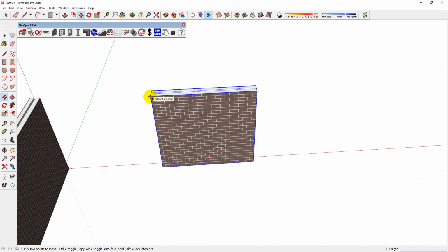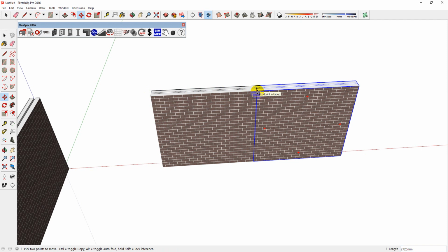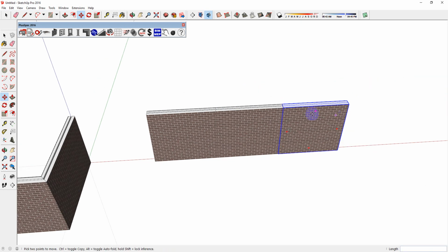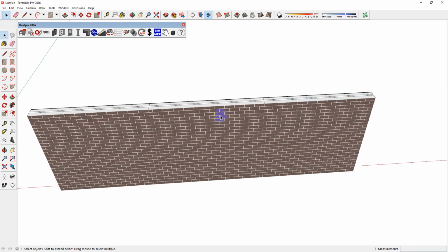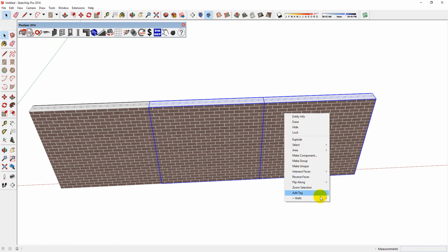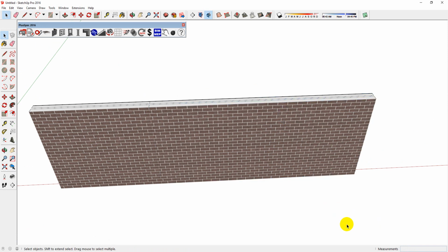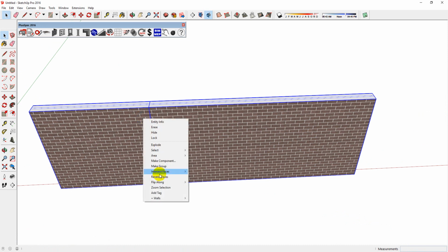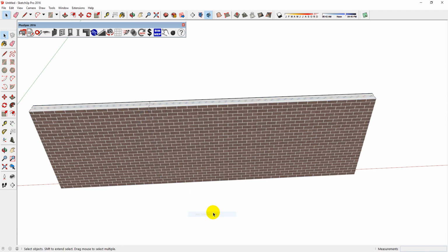Let's make a copy of this wall. In fact, we'll make another one. Join walls and meld walls are used for walls that are side by side. To do it, simply select the walls that you want to join or meld. See how the join walls keeps them separate, but it does understand that they are connected, whereas the meld actually turns it into one wall.